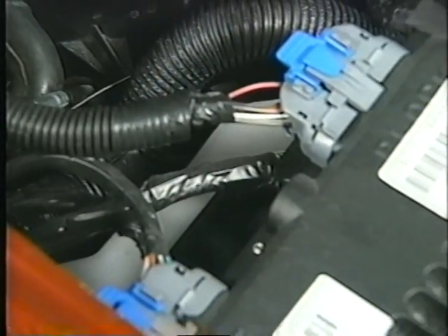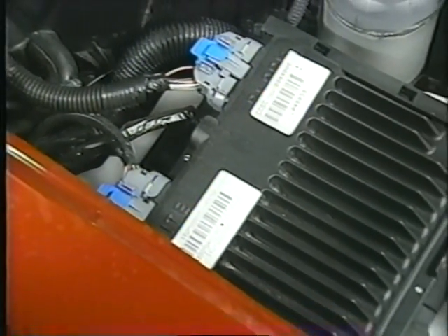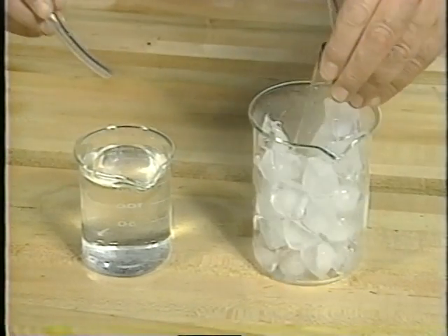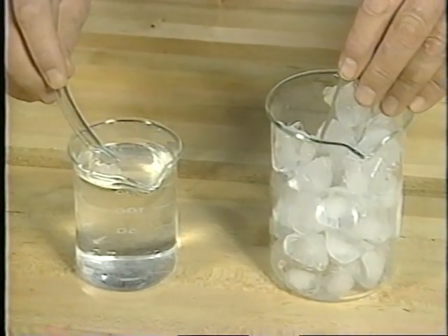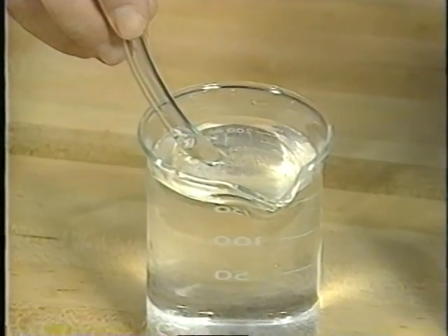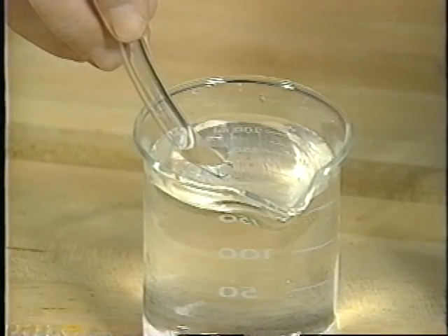Because the electrical connectors are environmentally sealed, the air flows all the way to the PCM connector before it finds a place to escape to the atmosphere. Then, when everything cools down, a partial vacuum is created, up to 9 psi, which draws air back through the same path. Well, this is okay, unless moisture happens to get in with the air.